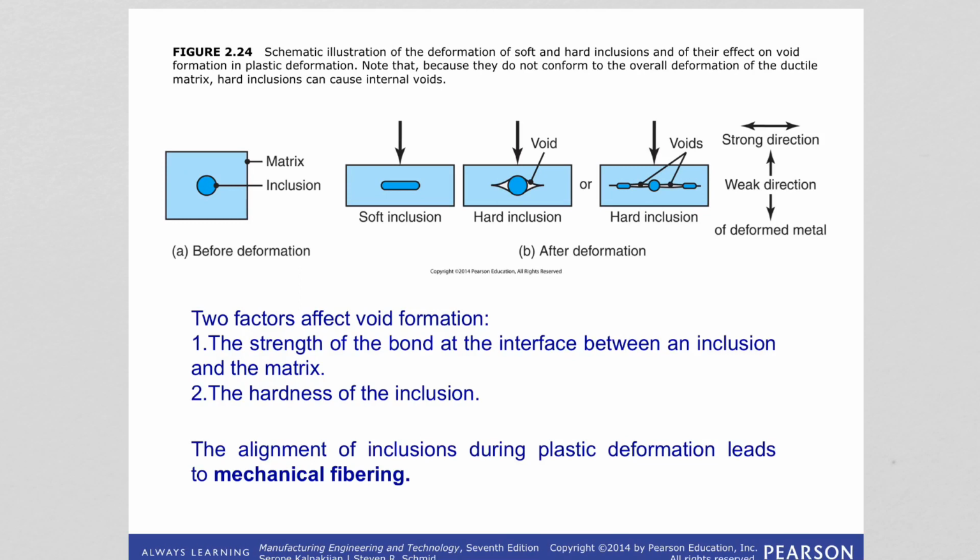So, because the nucleation sites for voids have inclusions. And what are inclusions? The inclusions are usually oxides, carbides, sulfides that are already in the structure. And these are responsible for the formation of voids, right? So these are very important in manufacturing, because they can be the reasons why we have defects, or they can be the reasons why the material fails during manufacturing.